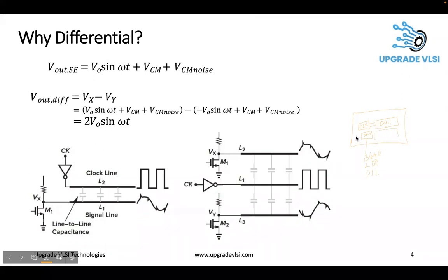So like that, it is placed somewhere here, and this clock might be routed close to the PMU unit. Okay, and this is one such diagram. So this is the CS stage. Its output is analog in nature, so that is routed to some other block. And here the clock is going. The clock will be continuously switching. So these two lines are routed very close to each other.